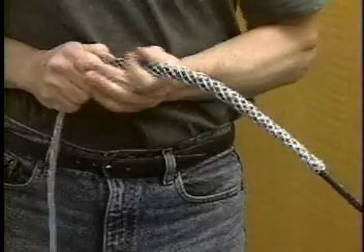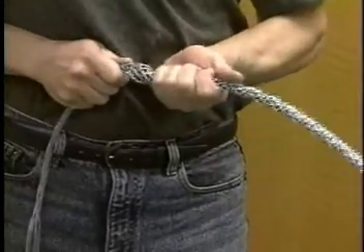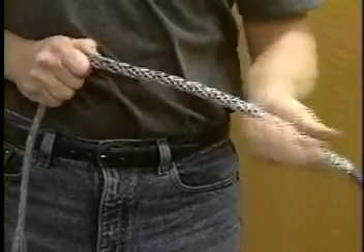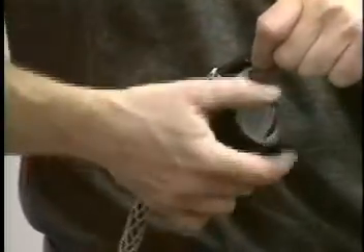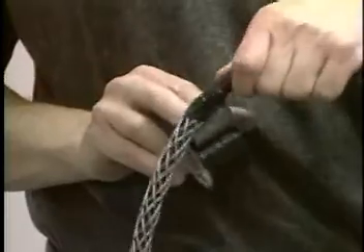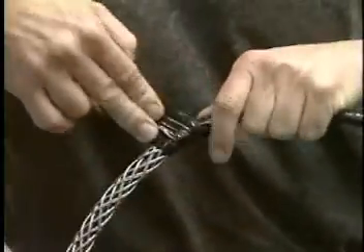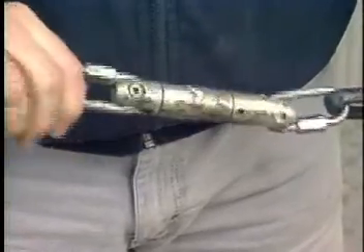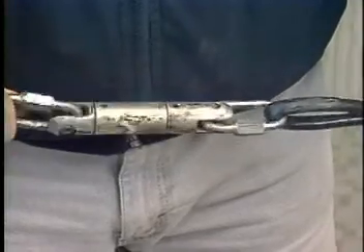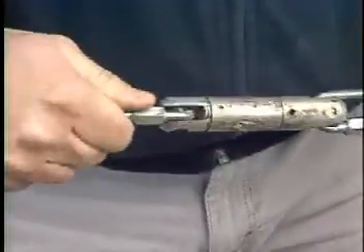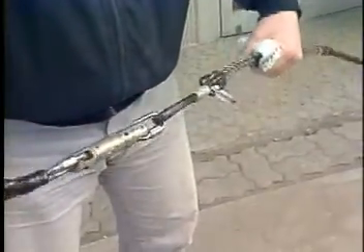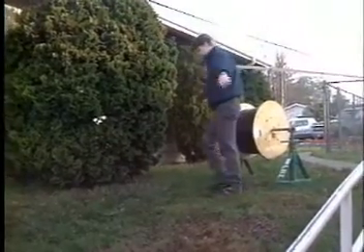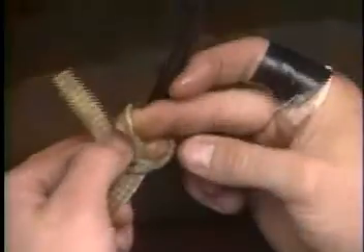The grip is chosen to match the cable characteristics and will spread pulling forces over a 1/2 to 1 meter length of cable. When the grip is in place, it is usually covered with electrical tape to reduce friction during pulling. A swivel should be added to the pulling line to prevent the cable from twisting. Because of the concentration of stresses where the cable attaches to the pulling line, after the cable is installed, the first 3 meters of cable should be cut off and discarded.